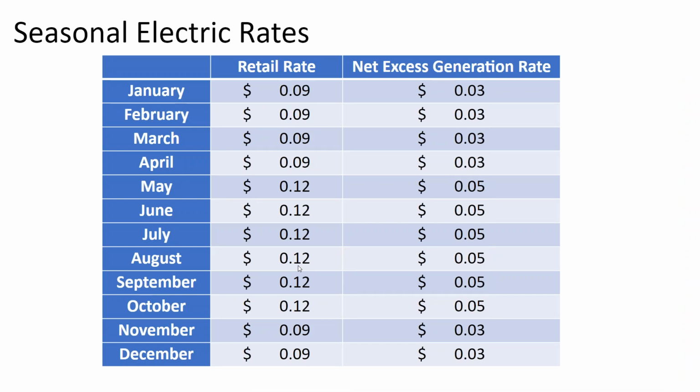What I would say is at the residential level, there is really no harm in new construction in doing a little bit of oversizing. And then at the commercial level, you're not doing a solar array to do the whole electric bill anyway. With commercial, you're really going after peak load. And so for residential, if you're looking at array sizes of 12 kilowatts for 3,000 square foot homes, I'd say that's good enough.